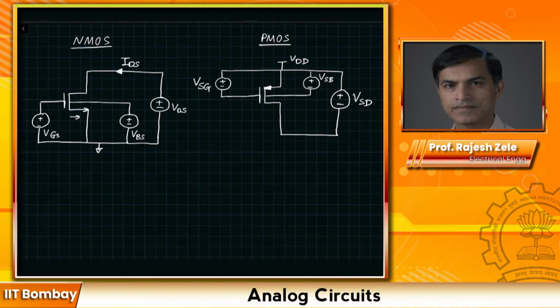Okay, on the right side, here is a trick that I like to use to keep things simple. Instead of calling it VGS, I like to call it VSG. And everything nicely falls in place in terms of equations. Otherwise, you have to deal with a whole bunch of negative signs here and there. Okay, so follow my train of thought here.